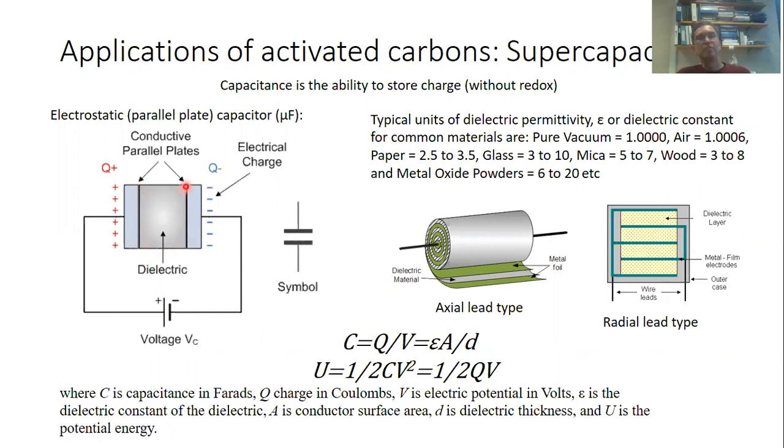In particular, the polarizability, which is associated with the so-called dielectric constant of that particular dielectric. So generally, the higher the dielectric constant of the dielectric, the more polarizable that dielectric is, and the more charges can therefore be separated. For that reason, the more charges are actually accumulating on the metal plates.